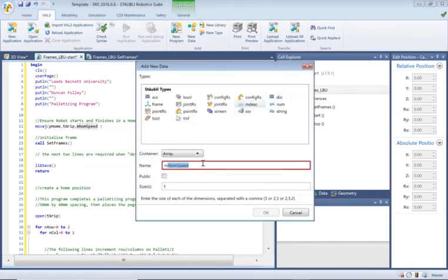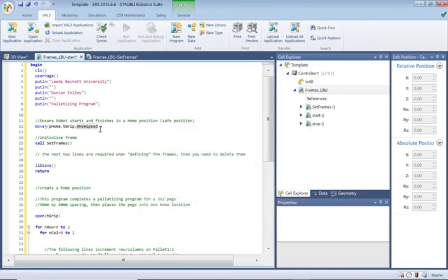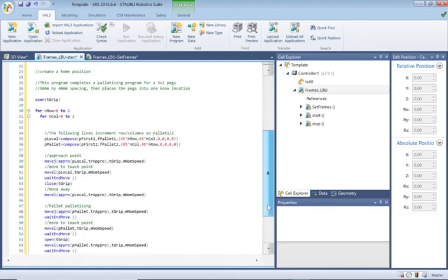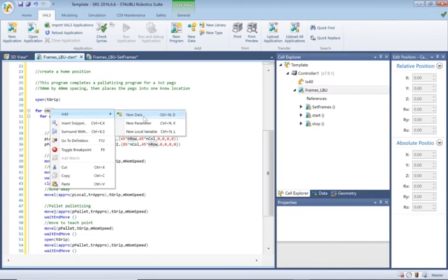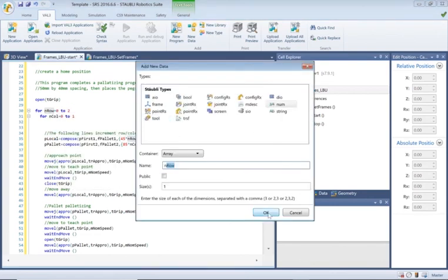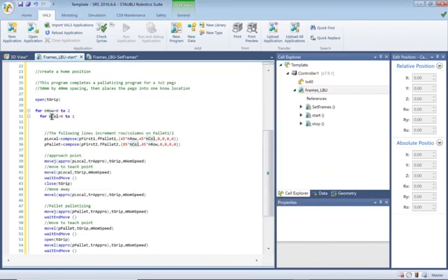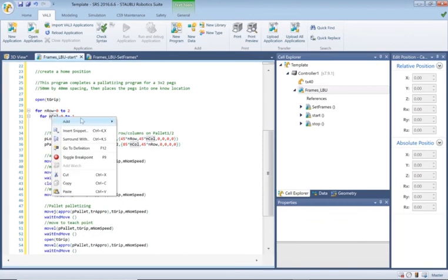So we have a motion descriptor. It looks like I've used this motion descriptor before. I'm just going to put the number 2 on there. It's going to default to the default speed and stuff. Just going to take that bracket off. Moving down, so we're going to define the gripper. Let's have a look. And this is just a little counters, so the little num variables again. Yeah, it's picking it up. This is a benefit of using the right sort of naming convention.